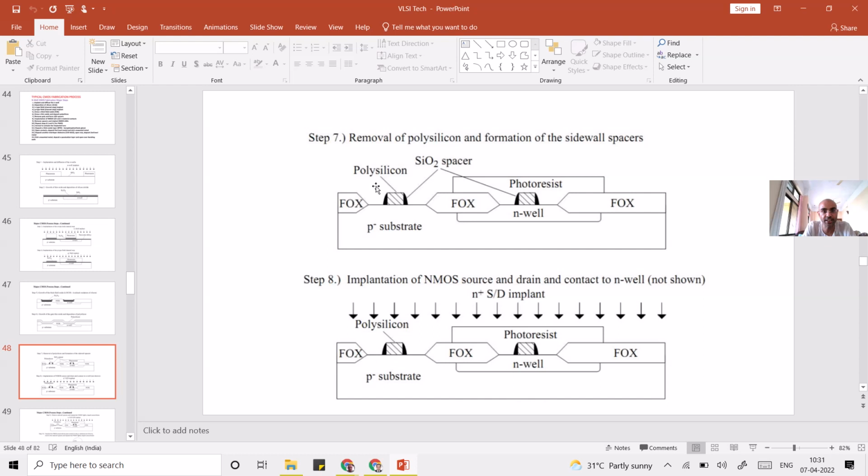So gate oxide and the polysilicon is over there. Apart from that, just to cover that this encroachment should not happen too much into this region, you put this SiO2 spacer. That is the reason to put this SiO2 spacer here. The SiO2 spacer lets you more finely control that encroachment, if there will be certain encroachment. Okay, if it goes somewhat under this region as well, then